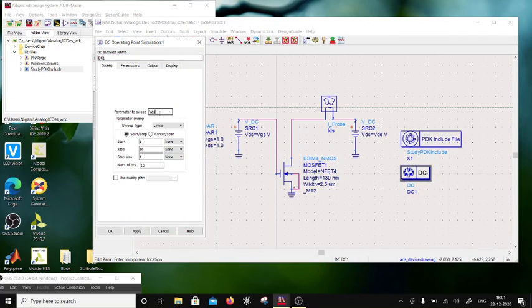So I'm going to sweep a VDS from 0 to, let's say, 2.4 volts. Let me tell you, there are two threshold devices here. One is a smaller threshold device which is used for high speed applications, and this is also a 1.2 volt device. The nominal supply voltage is expected to be 1.2 to 1.8, but the device drain source junction breaks down around 2.2 volts. So you can use this up to 1.8 volts as a supply.